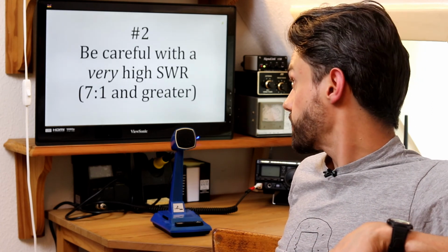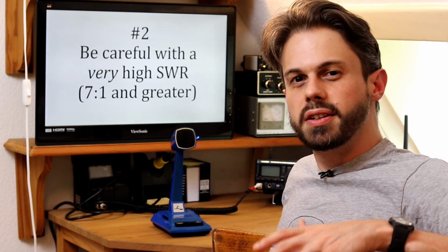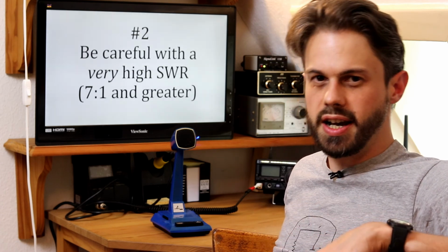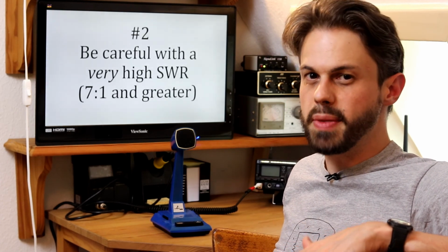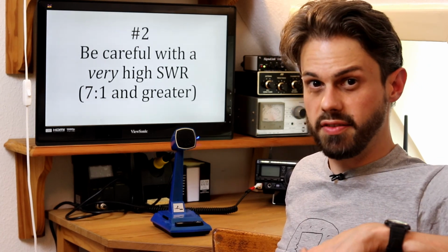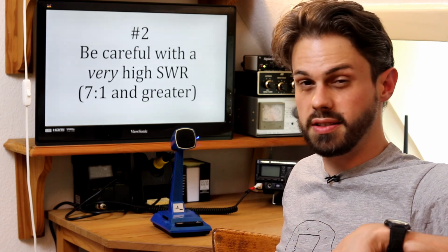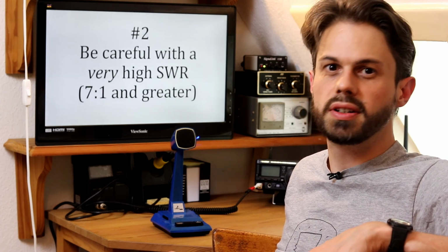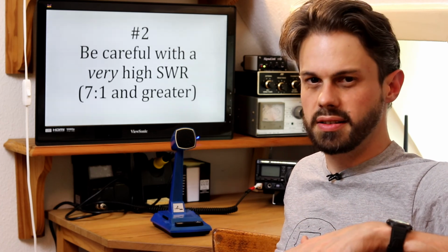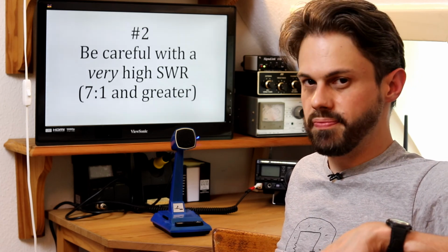Second lesson, be careful with a very high SWR. Of course, your transceiver won't like it. If you have a very, very high SWR, it can be really bad for the electronics in your transceiver, even though modern transceivers have a protection circuit that reduces the power once the SWR gets too high. But still, it's not a good idea. Besides, if your SWR really skyrockets, the losses will manifest. So there you have a problem.